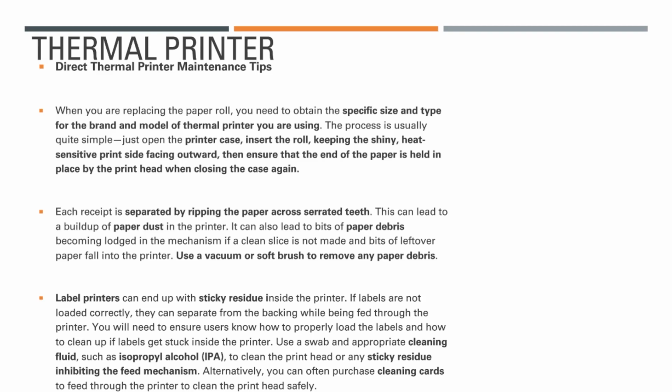Each receipt is separated by ripping the paper across serrated teeth. This can lead to a buildup of paper dust in the printer. It can also lead to bits of paper debris becoming lodged in the mechanism. If a clean slice is not made and bits of leftover paper fall into the printer, use a vacuum or soft brush to remove any paper debris.